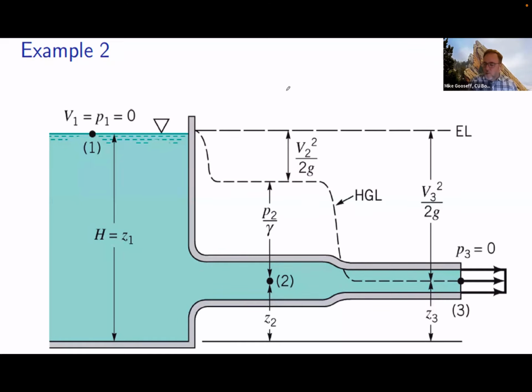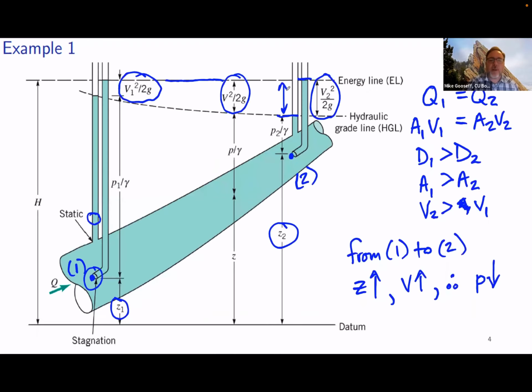Okay, so clarify something from that last slide. Sure. Let's see if I can go back there. There we go. I thought for stagnation tubes the velocity was 0 right at like the entrance, and now we're talking. Yeah, good. So that's a good question. So what's actually happening here is there is still a full pressure, a full energy that is represented there.